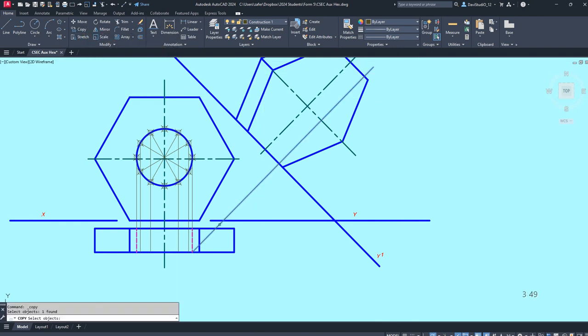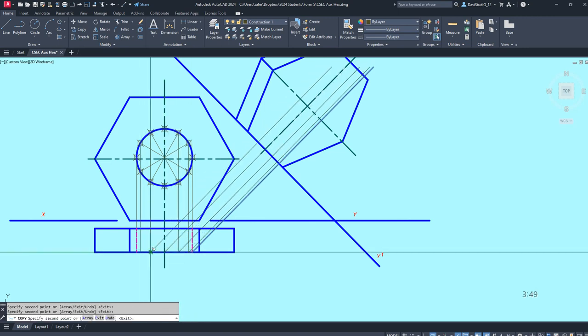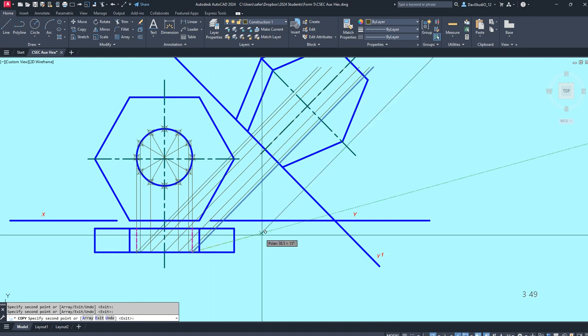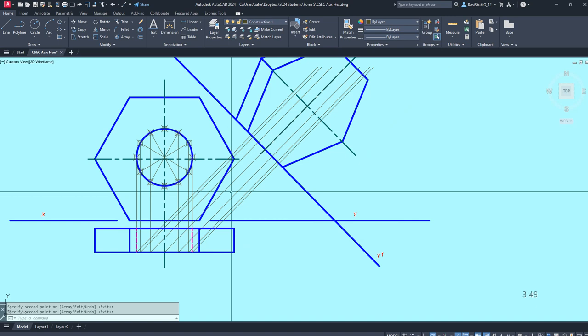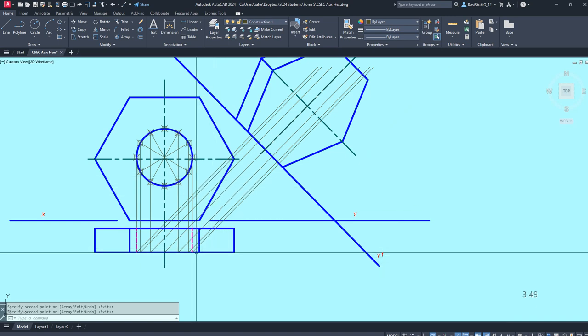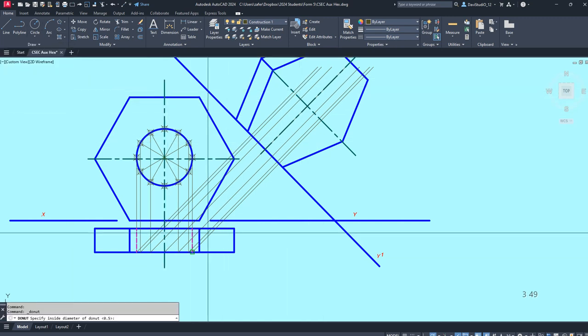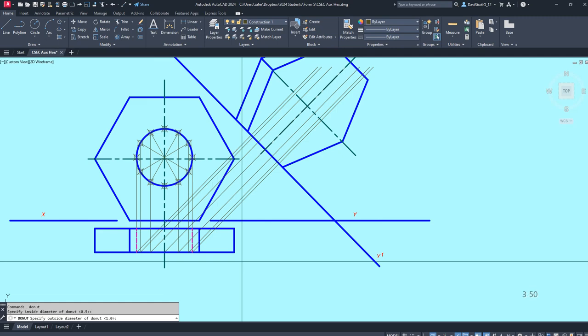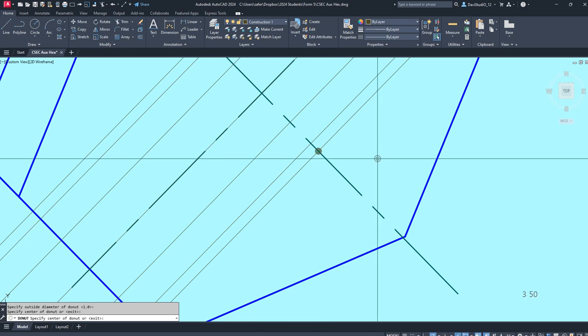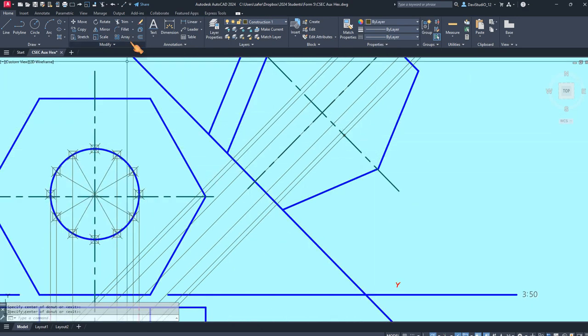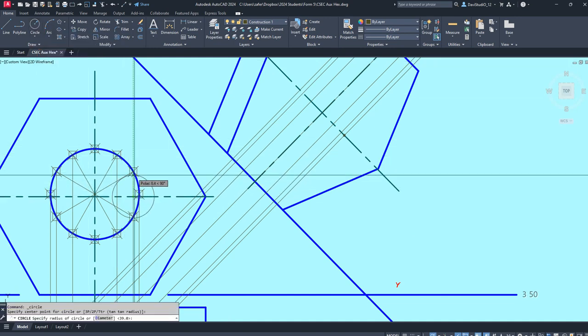copy. Alright, again we use our trusty donut. This first line here is on the center line, so you can use a donut. Internal diameter 0.5, external diameter 1, and put our donut here. Now to get the next point, as what we did previously, you want the distance from here to here.